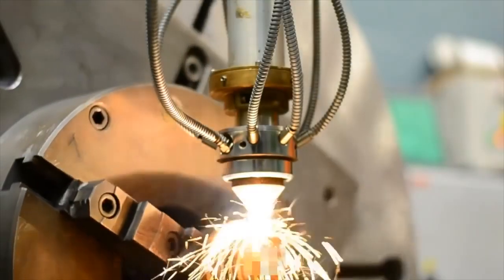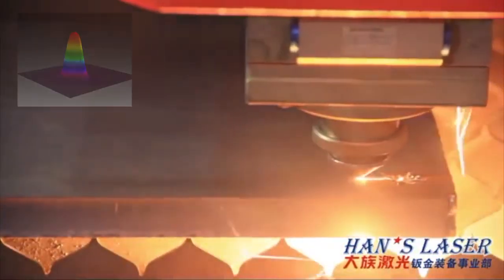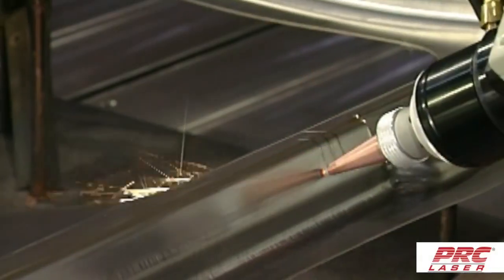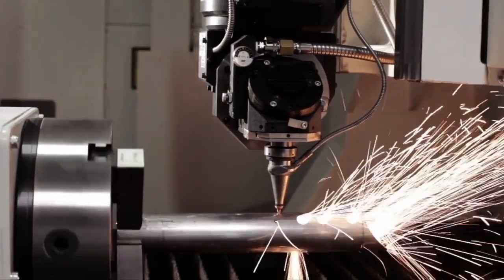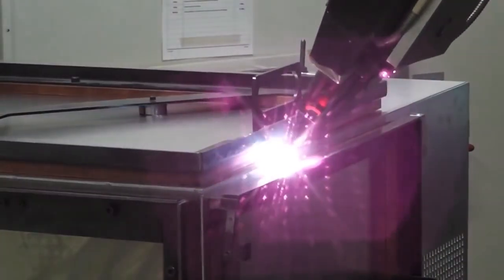Each laser application requires specific laser beam characteristics. For example, in material processing, cutting steel requires a different laser beam profile than cutting aluminum. The distribution of the power and energy density in the beam determines the effectiveness of the laser at the work surface. Even the smallest deviations in beam adjustment or focal position may lead to massive increases in scrapped material and pollution of the environment in a variety of ways.